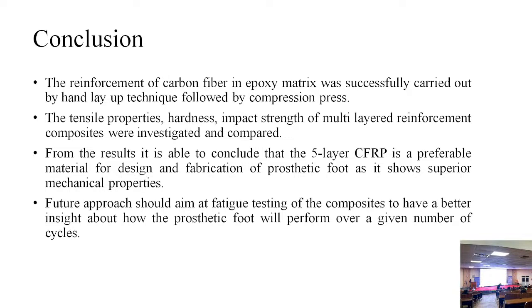The properties such as tensile strength, hardness and impact strength were investigated and compared, and from the results it is possible to conclude that the 5-layer carbon fiber reinforced polymer is the preferable material for design and fabrication of the prosthetic foot as it shows very superior mechanical properties. The aim of the future investigation is fatigue testing of the components so that we can know how the prosthetic foot will perform over a given number of cycles, to investigate the durability.